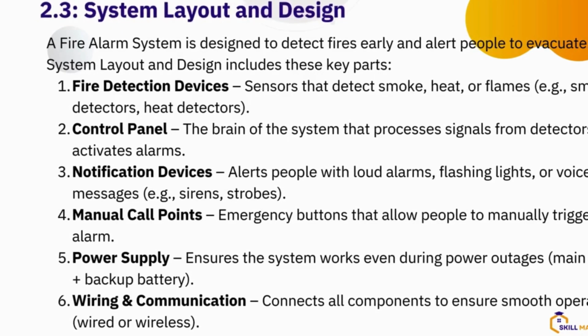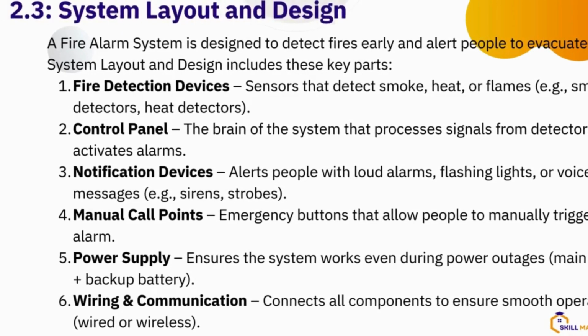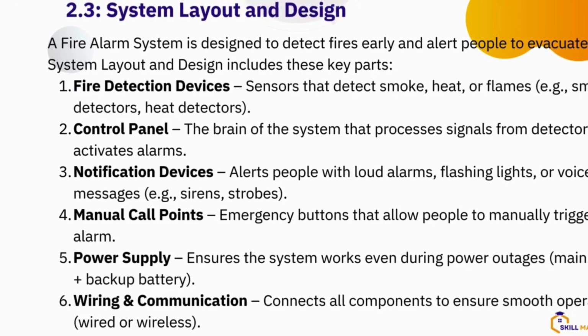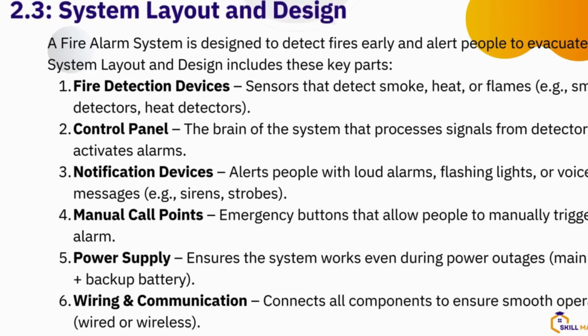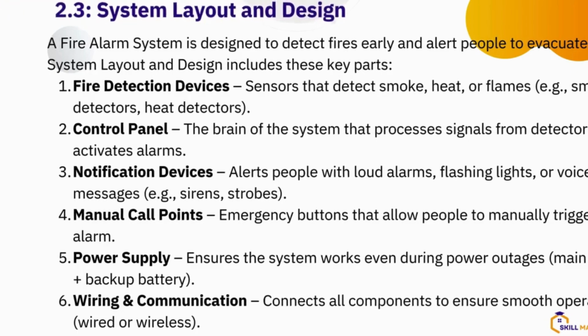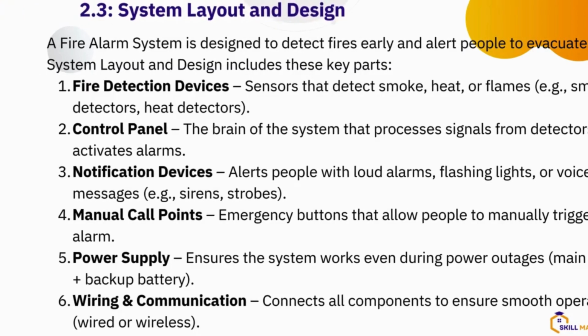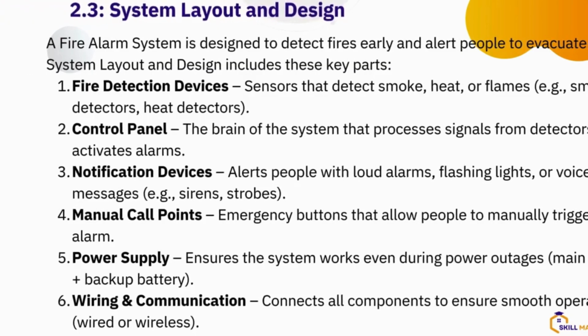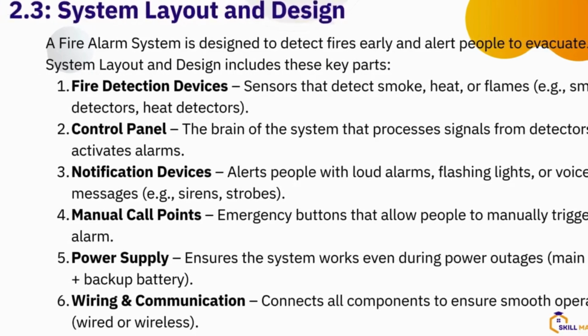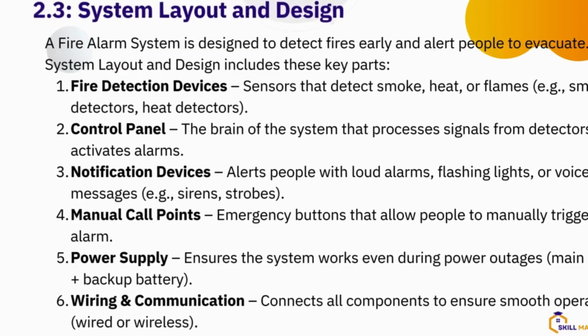Like I said, it's advisable you deploy your MCP at the exit point, maybe on the corridor, at the door, outside the structure, so somebody can press and escape. Because when there's a fire outbreak, everybody's mind is to escape. So the MCP should be at the point where you can press and escape.